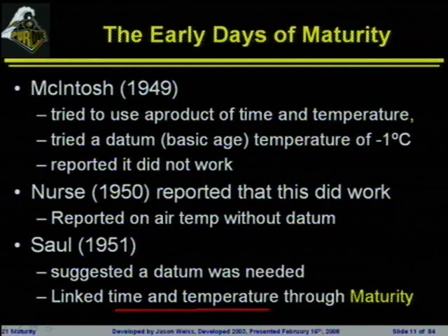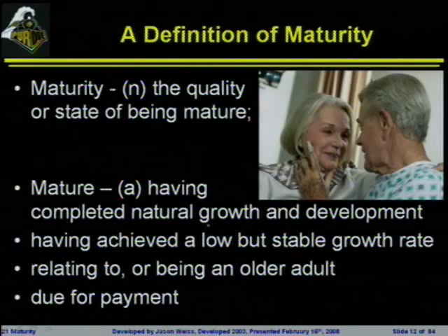So earlier in the semester we talked about degree of hydration. And degree of hydration was what? How much of the cement has reacted? So you start out with 0 degree of hydration, none of the cement has reacted. 100% of hydration, all of the cement has reacted. You've got a structure inside of the material. What they're saying here is the rate at which that reaction actually occurs, the rate at which the material hydrates, is going to be related to the temperature the concrete is conditioned at.